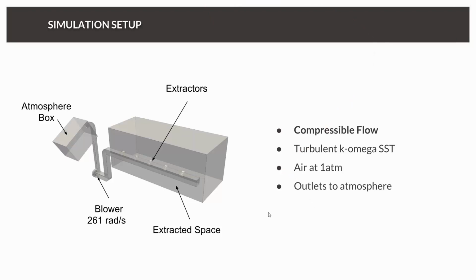And here on the right side you can see some of the most important boundary conditions. So it's a compressible flow. It's also a turbulent flow, therefore we have to use what we call a turbulence model. I don't want to talk too much about theory, but maybe this is an important point and a point where a lot of confusion is happening. Turbulence is a phenomenon which is not 100% understood until today. And since you would need a nearly unlimited amount of computing power to solve turbulence, we use turbulence models, which simplify the effort of calculating the turbulent parameters.